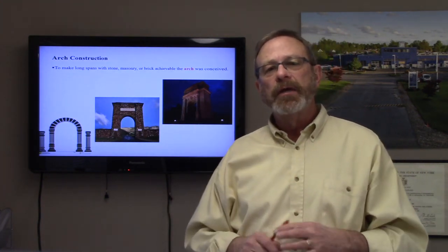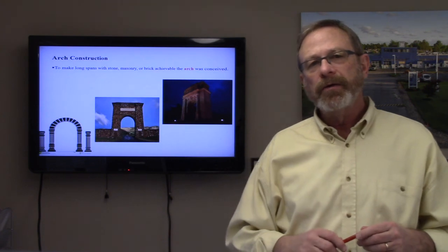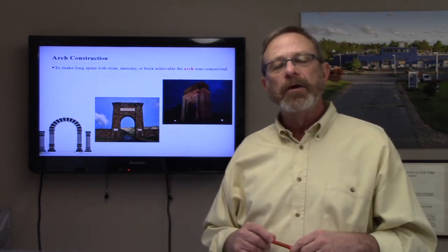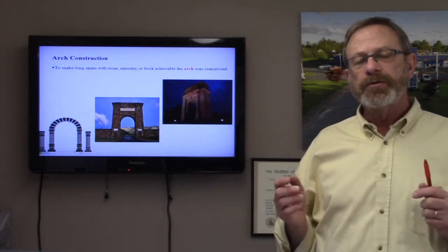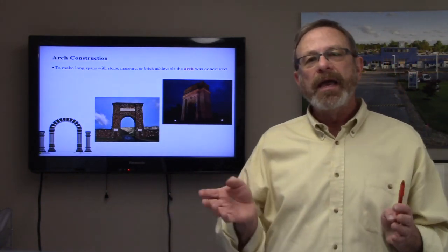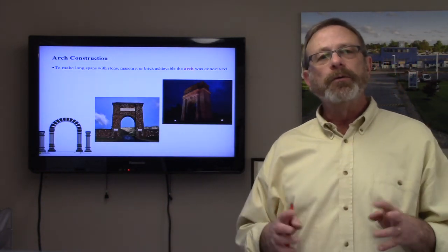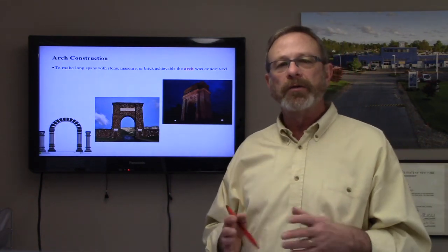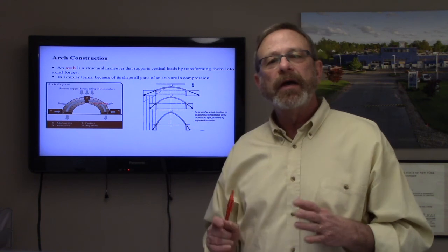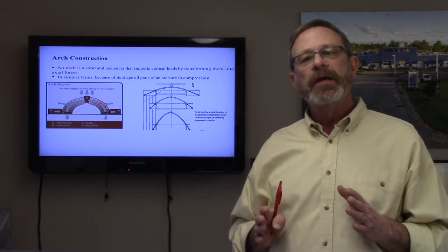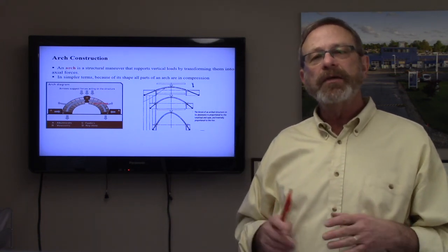By experimentation, someone developed this arch idea, and arches are the compressive structures most commonly used today to span large distances. They came into existence around 100 AD during the Roman era of bridge building. It's very supportive of weight and long span. So it was a good use of compressive granular materials, which they had. You can think of an arch as consisting of two halves that lean one against the other at the keystone.